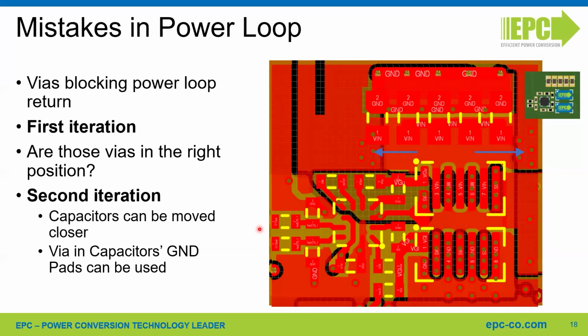Each FET needs to have its own gate resistors, and so avoid paralleling the gate directly between the devices. And we have seen up to 4 parallel devices. We can have a good solution to share a single gate driver among 4 parallel devices by paralleling 4 half bridges.